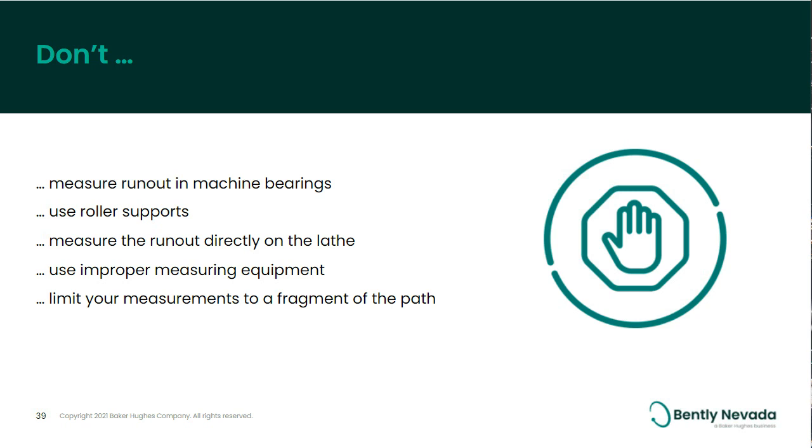It could be a certain amount on either side of that. So if you know that the shaft can potentially move axially, make sure you take a couple of measurements along that full target surface area. Make sure that there are no deviations on either extreme of that probe target path.